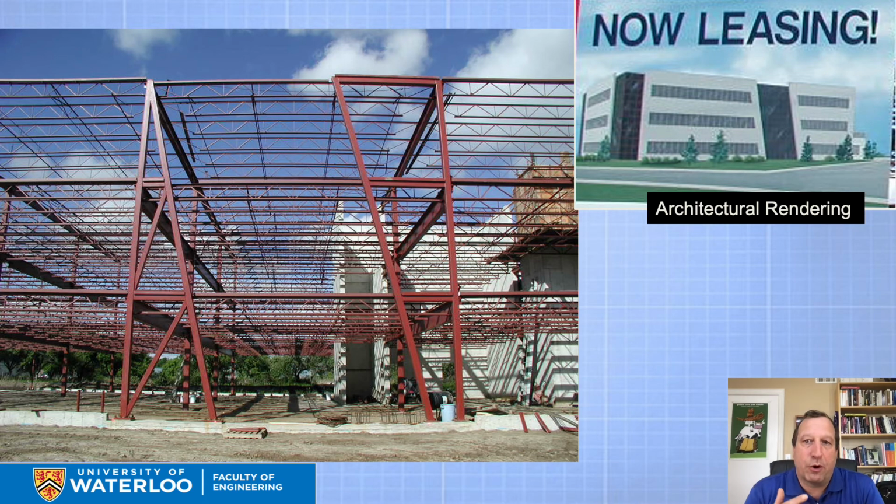And you can get more creative than that. These are examples where the X-braces are built into the left-hand HSS frame, and that HSS frame is also acting as the columns, but it's looking like that because the architectural vision was to provide these sloped glazing units that you see on the right-hand side. So that's a diagonal drawing there.